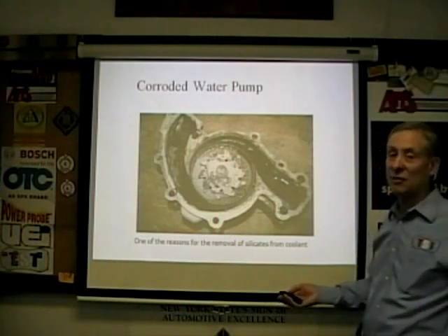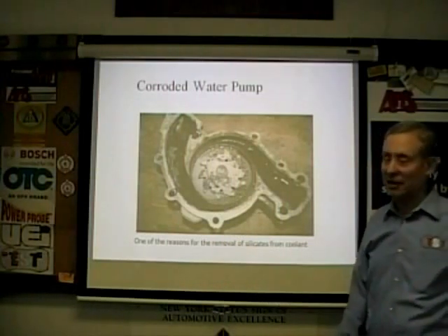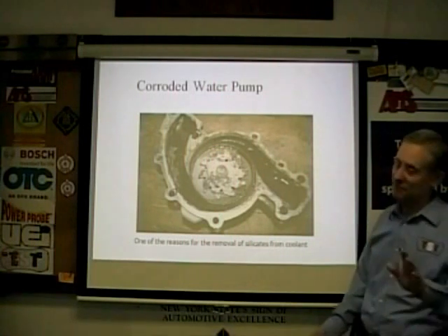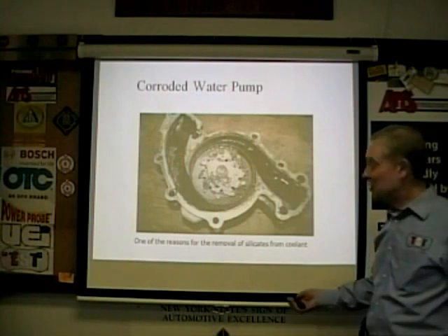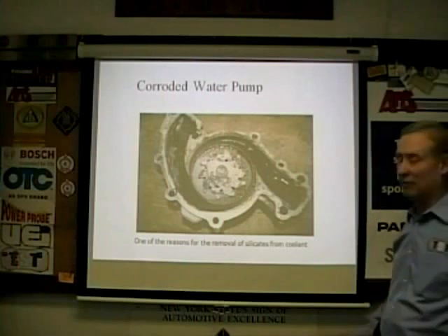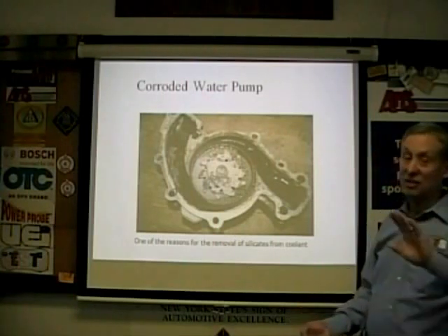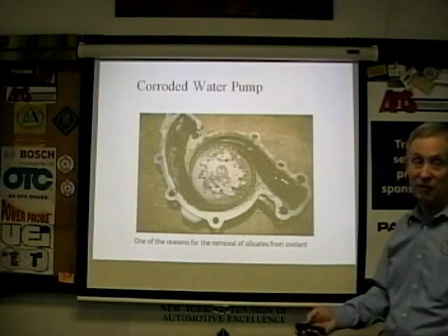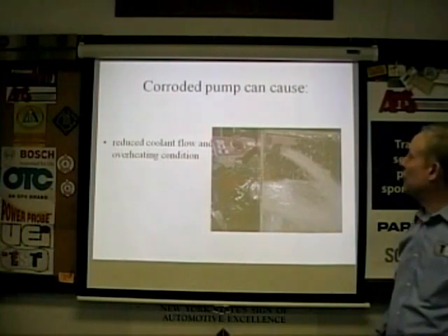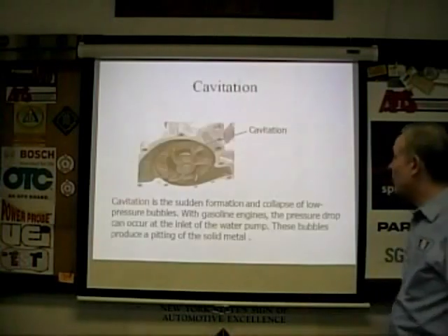And of course, with modern cars, we have the plastic impellers. VW has them, BMW had them, and you end up with compatibility issues. Some of the time, that stuff isn't breaking just because the plastic was garbage, which it was, but some of the time it was breaking because people put the wrong coolant in and it weakened the plastic. It made it brittle. Right, or put some additives in, so there were solids or precipitates or things that it couldn't push, and it was flexing that thing and breaking it. All right, reduced coolant flow and overheating. We can get corrosion. I mean, this is stuff we kind of know, basic stuff. You don't want problems with it.